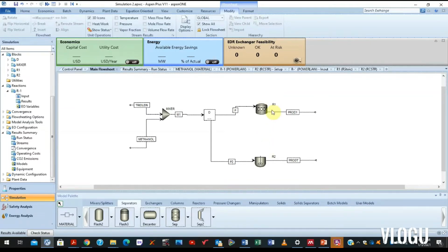Welcome to the continuation of our series into the simplified modeling process for biodiesel production using methanol and triolein, very straightforward. Simple process, right? Now, previously we had shown that you could actually utilize, in this particular case, the RStoic and the RCSTR reactors, right? We had described or defined the specifications for each of the reactor types, explained the uses for each reactor type, as a basis for predictive estimation of the yield, and non-predictive estimation, where you have an idea of the stoichiometry and the conversions of the reactor, right?